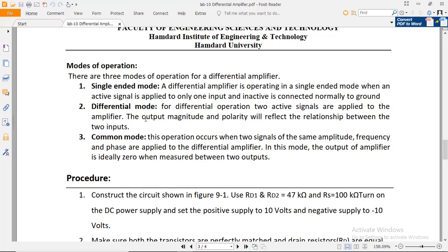We provide the supply from VG1 and VG2. Both supplies can have voltage levels going up and down. Both supplies need not be the same in magnitude, and they can be provided with a difference of amplitude but with opposite sign. This is the main thing that gives us the differential mode in a differential amplifier.